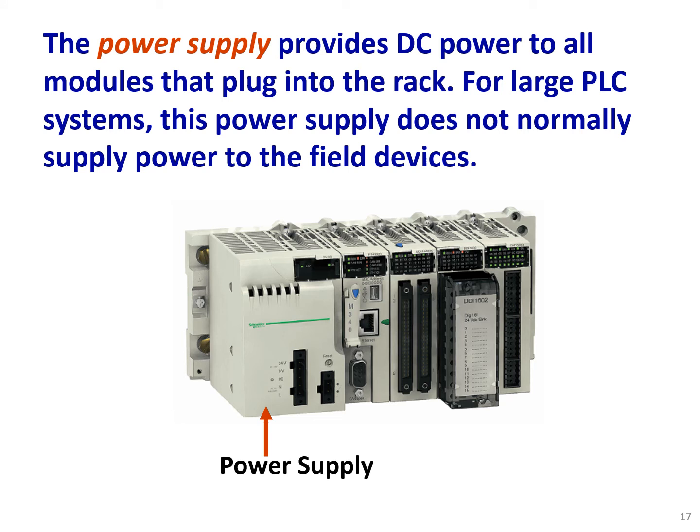The power supply provides DC power to all modules that plug into the rack. For large PLC systems, this power supply doesn't normally supply power to the field devices. Okay, so here we have the power supply, and here we have the CPU, and then we have input output modules that we could add on the rack.